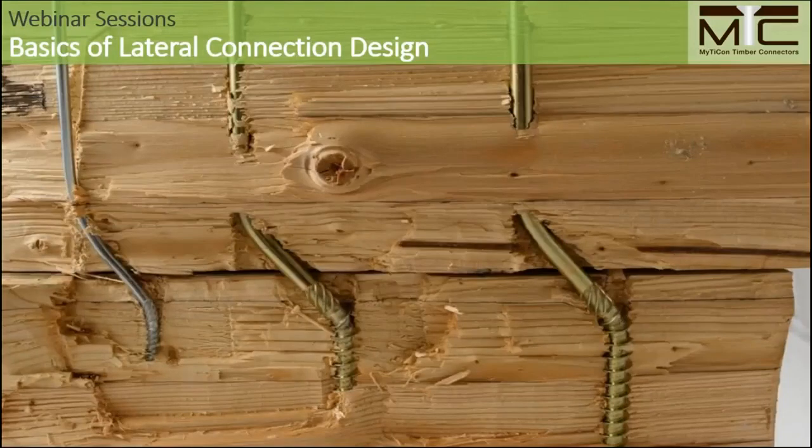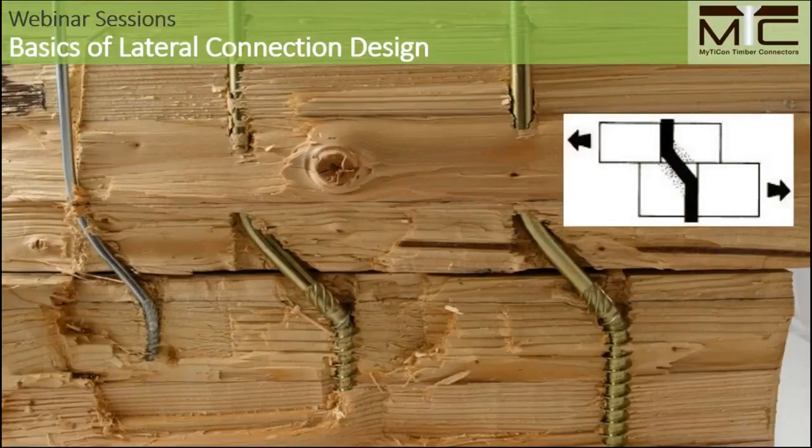On this slide, it can be nicely seen how this failure mode 4 looks in real life. This was a little dummy test that we did at UBC here in Vancouver, and you can nicely see the formation of the plastic hinge inside the main member, and localized wood crushing effects along the shear plane. This is a very classical failure mode 4 here.